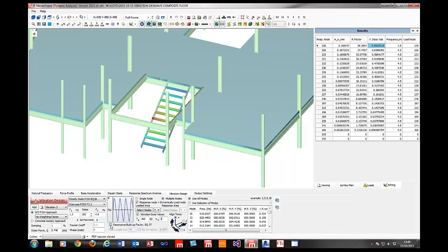And the reason why that's important is because when somebody starts interacting with a structure, walking on a structure, the structure doesn't immediately develop into this steady state sinusoidal type of movement. It has to build up to it. So it starts off from not moving at all, and then the sinusoidal movement builds up until it reaches this steady, constant sinusoidal movement where that's applicable. And that build up can be taken into account. So really, this is saying, well, the activity might not have enough duration to develop the full steady state response. So therefore, let's look at how that can influence things.